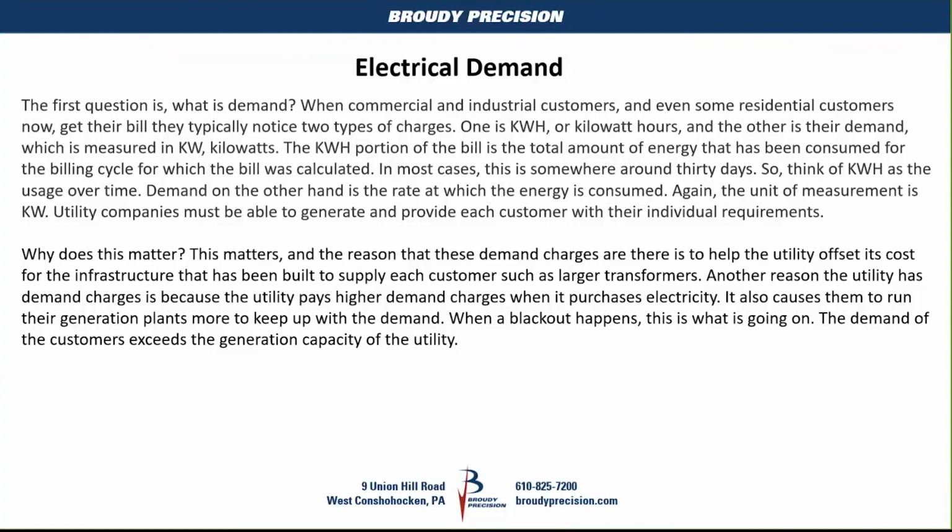That one bulb would consume 72,000 watt hours, or 72 kilowatt hours. So that works out to 100 times 24 hours times 30 days, which is 72,000 watts divided by 1,000 equals 72 kilowatt hours. So that's all well and good.